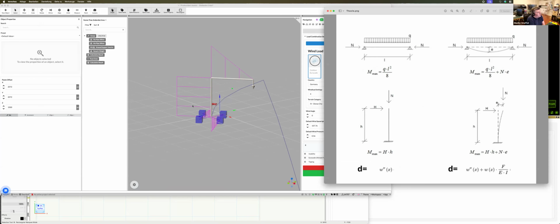When you're doing a structural calculation, by default, you are calculating the forces and the reaction forces, shear forces, moments based on the undeformed shape. So effects like the structure actually bending a little bit to the side do not have effects on the forces that will be calculated.